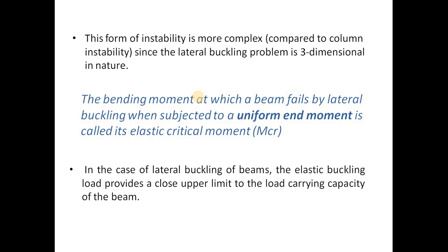This form of instability is more complex compared to the column instability, since the lateral buckling problem is three-dimensional in nature. It is not two-dimensional anymore.